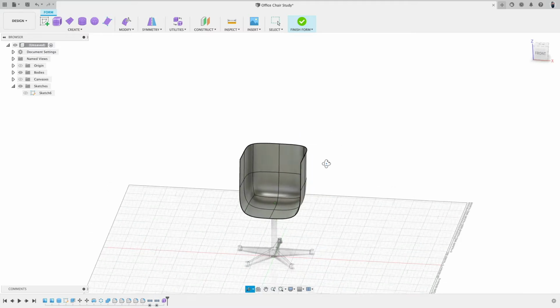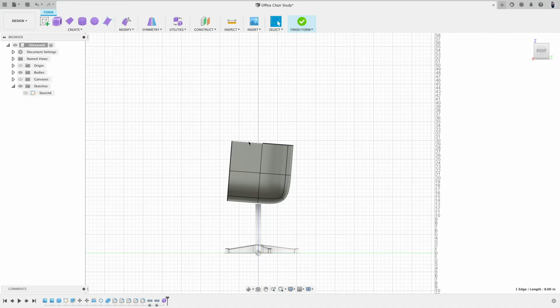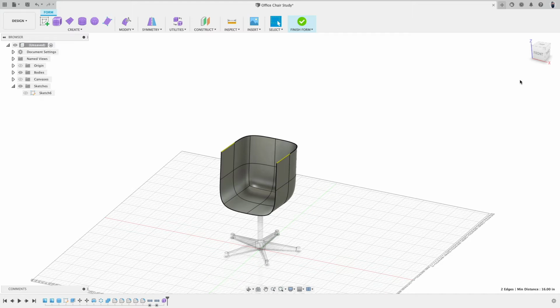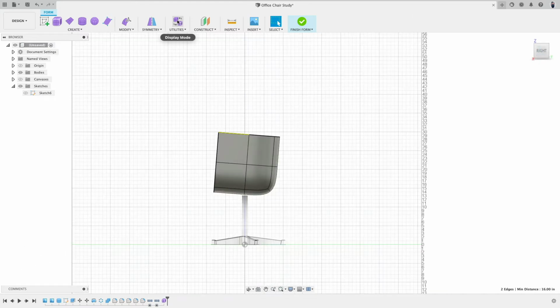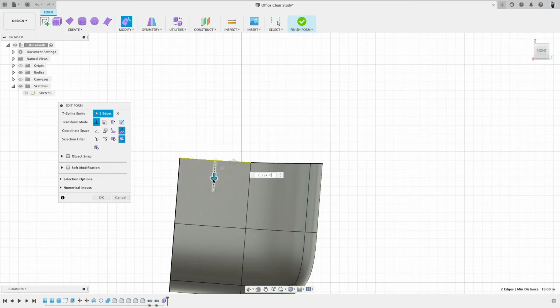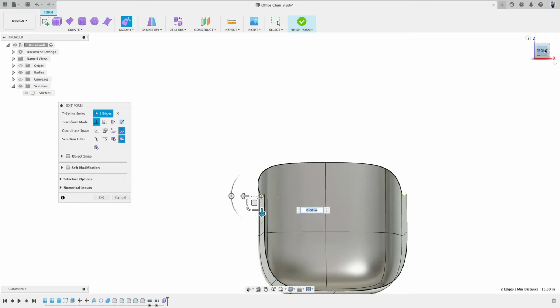these 8 faces, pretty much the same like before. And the next step is kind of cool what we're going to do. So we will select those. Very nice. And then we go to modify. And hold on one second. Local, yeah. So you see how this arrow is now perpendicular to this edge. That is what I wanted. Very good, because then it goes straight down.